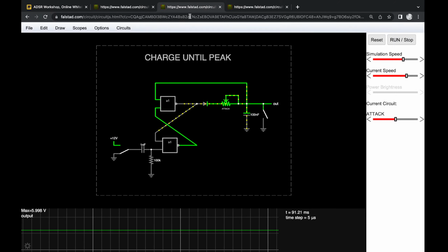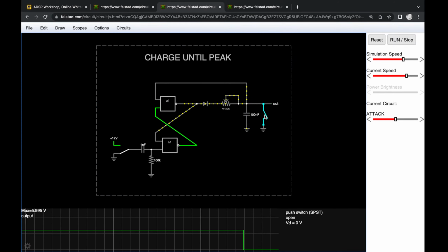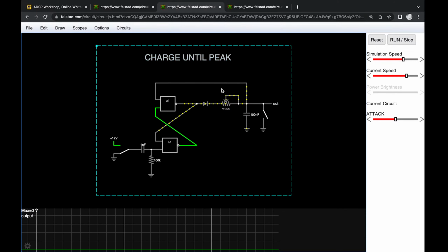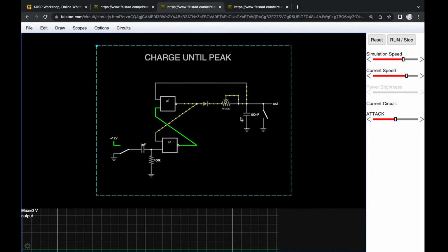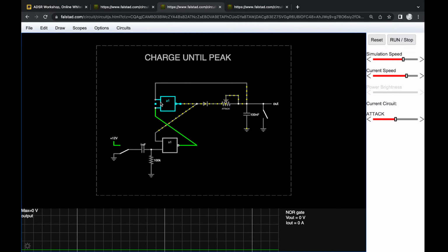So the problem that I'm talking about is a kind of scenario that we haven't thought about, which is the following. With our peak detection, what we rely on is the fact that this capacitor gets charged up to that peak level, and then this thing turns off, right? That's how we implement it.